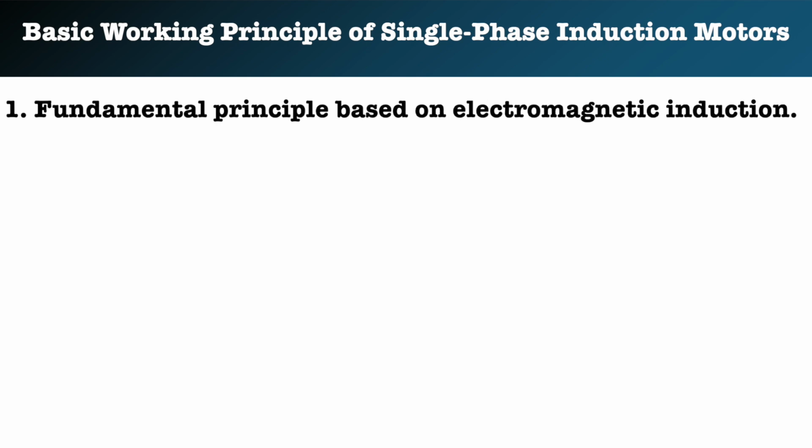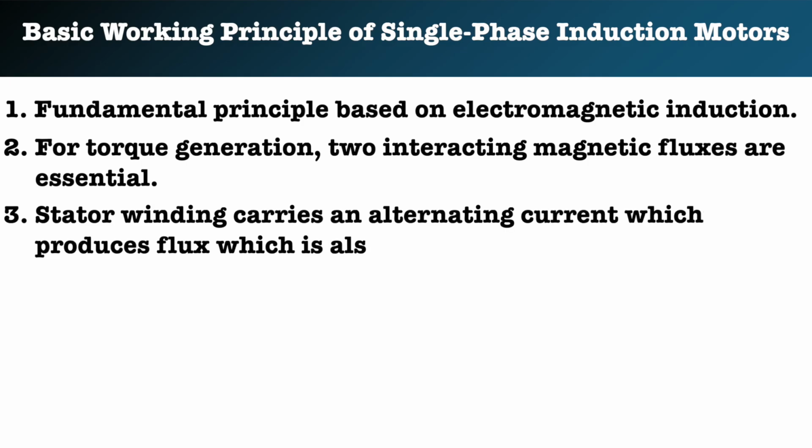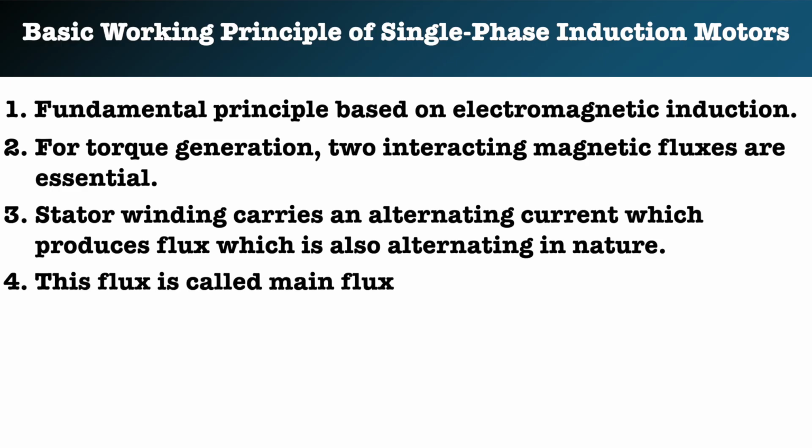The fundamental principle of single phase induction motor is based on electromagnetic induction. For torque generation, two interacting magnetic fields are required. The stator winding carries an alternating current which produces the flux, which is also alternating in nature, and this flux is known as the main flux.